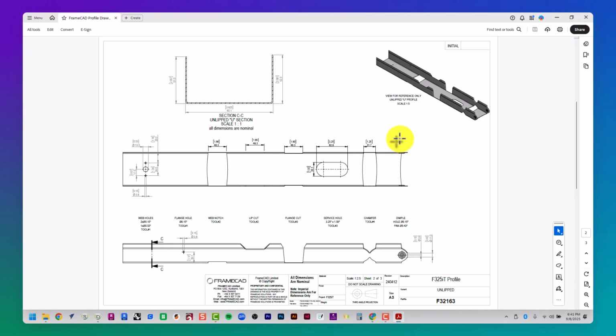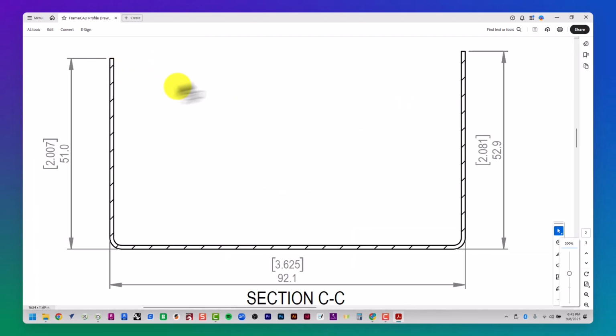Typically, with light gauge steel, you're either buying it at a box store, or you're buying it and creating it yourself using FrameCAD. When you buy it at a box store like Home Depot, Lowe's, any one of those places, you have to buy two different kinds. Okay, one is called the track, which would run your bottom plate, or it would be your top plate, and then the rest are called sticks, which are all of your vertical ones. So all of your bottom and top track have no lips, right? So that way your sticks can just fit perfectly right into them, and then you can attach them.